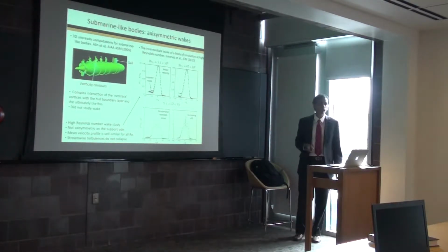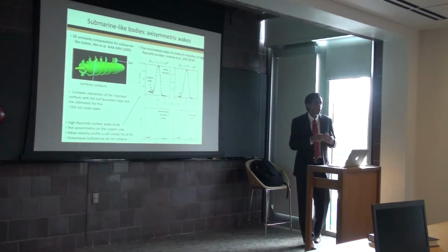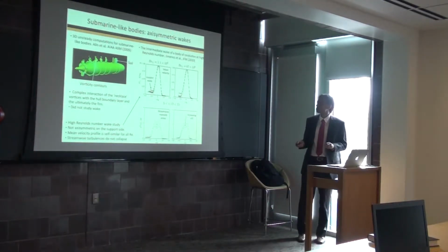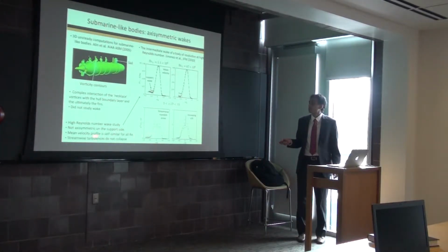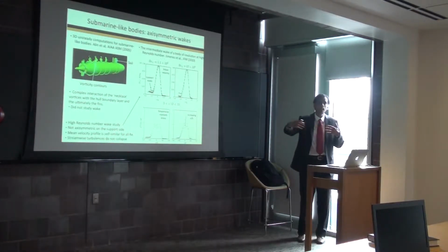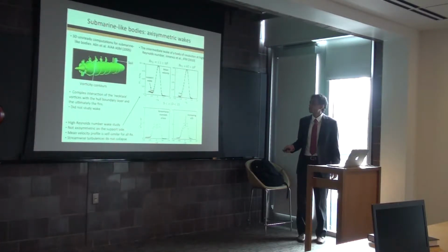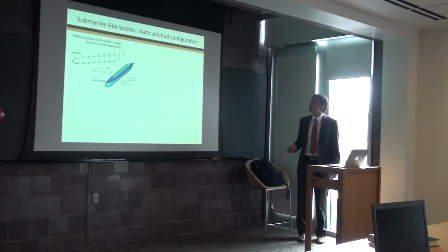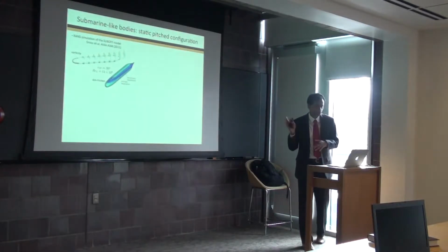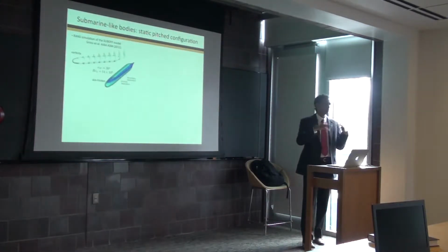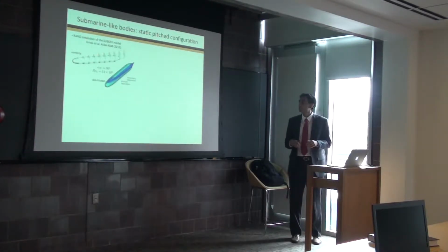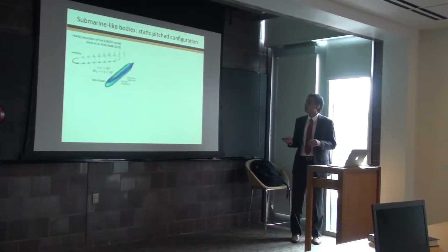Now, this is the mean velocity profile. The streamwise Reynolds stress did not collapse at all over the range of downstream locations that he looked at. So self-similarity was not reached. And so this might be a clue for us that these wakes have rather long development lengths, which make them also rather difficult to study. So this is what we know about axisymmetric wakes. Of course, that was just a very brief overview. Axisymmetric wakes have been studied in great detail over several decades.